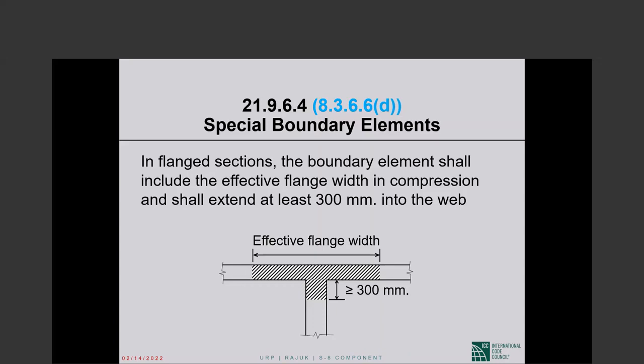At the very top, if the shear wall is discontinued, do you build a beam at the top? That may happen. It all depends on what you are trying to do and what the rest of your framing is. But this is the best answer I can give you. Along the height of the wall, at the different floor levels, you never try to build a beam inside the shear wall.